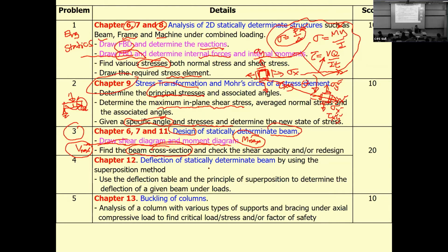For example, if you have a beam like this, subjected to a force like this, it will change its shape like this. If there is a wall under the beam, the deflected shape will compress the wall, and many times the wall can be cracked. So we need to prevent it by determining the so-called maximum deflection. This maximum deflection will be set less than L over 240 if there is no wall under the beam. If there is a wall under the beam, the maximum deflection will be less: you have to divide the span L by 360.